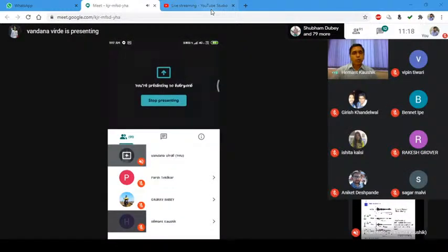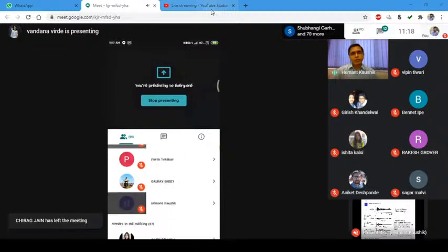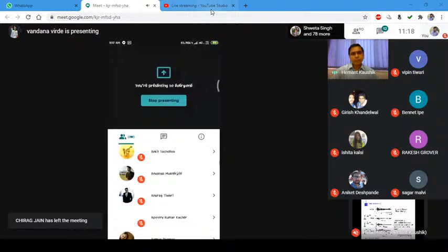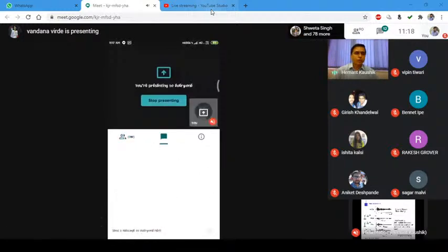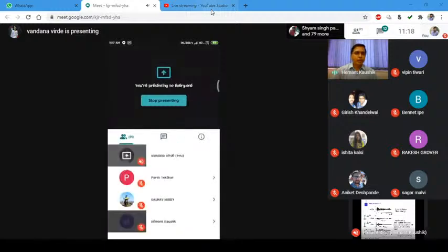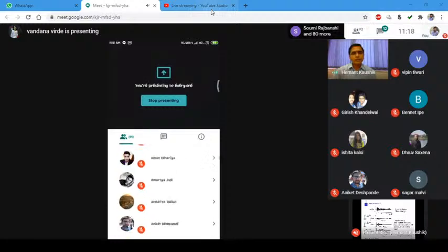Now you can ask, how will I get the maximum displacement here? Or forget about maximum, how will I get the displacement at every instance of time? Because it is not done experimentally. It is theoretical calculation. The answer is very simple. You know the equation of motion of the single degree of freedom system subjected to base excitation, right?